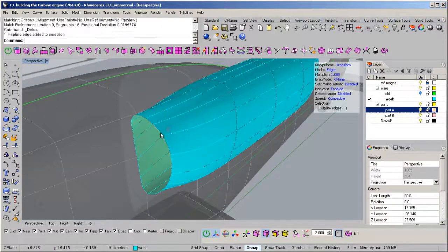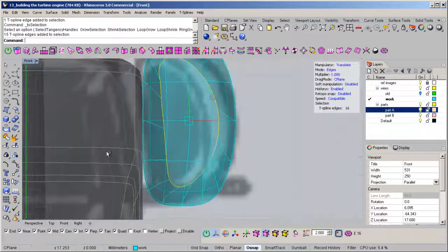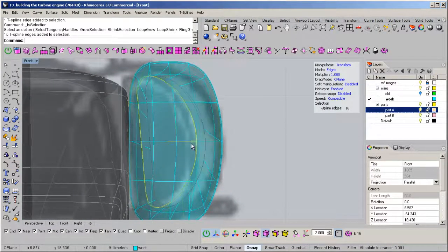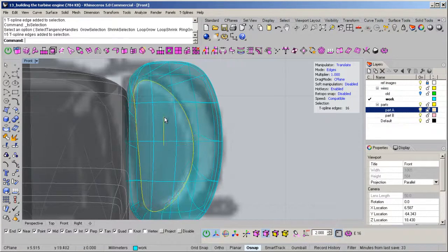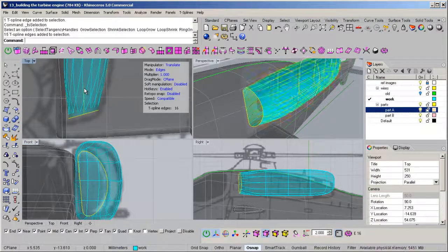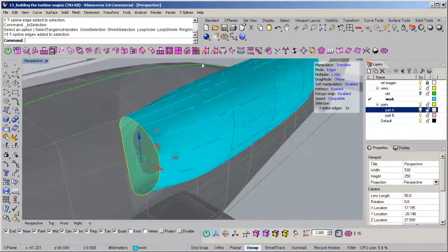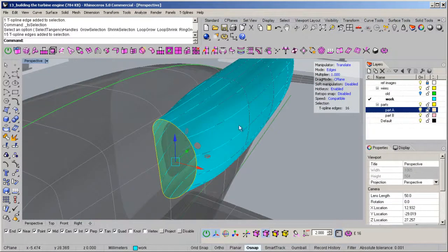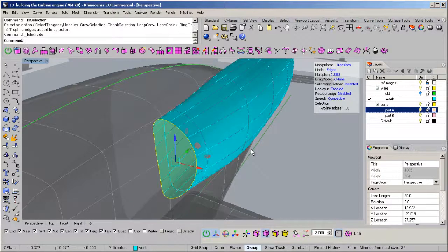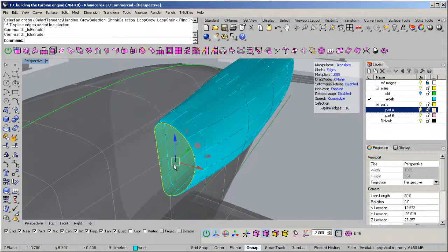You can select this ring. Make sure it still looks the way we want it on the concept, so we need to pull it in just a tiny bit and pull it down. Make sure the angle is still right, so I'm quite happy with it. With the edges still selected, I can go here now and do an extrusion. Hit the scale key so we can pull it in. Hit enter again so we can do it one more time.